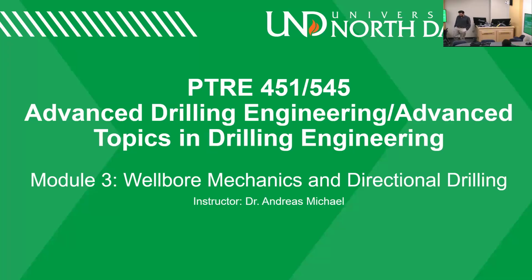Also, something that I forgot to say when I was talking about the U-tube model is that in real life, things are not like what we see in class. For instance, I talked about a stabilized shut-in drill pipe pressure. But what if that's changing too? We don't expect it to change, but it could in real life. It means the kick is moving or expanding quite fast, so it's pushing on both sides. Theoretically, it should only change the SICP. But these things are possible in real life. In the real world, things change that you didn't expect to change, and you need to factor those into your decisions.